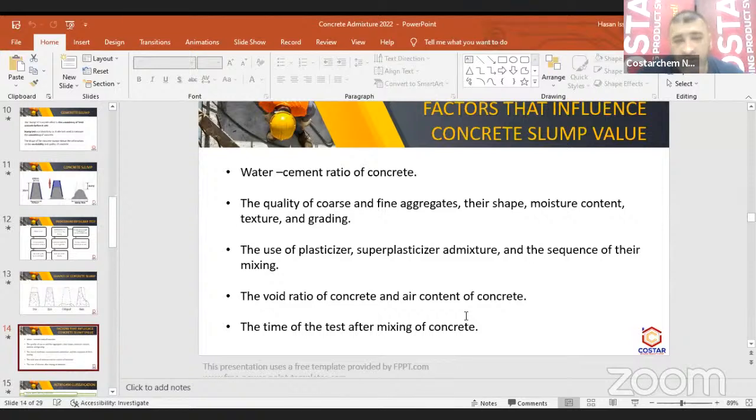Imagine, each one cubic meter of concrete can be 2,400 kilograms, and can be reduced to 600 kilograms. I'm not saying that's a different type of concreting. We call it lightweight concrete, but we can use air even to achieve that. Each concrete has its own type of use. There's no bad concrete.